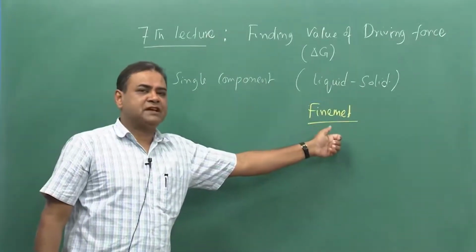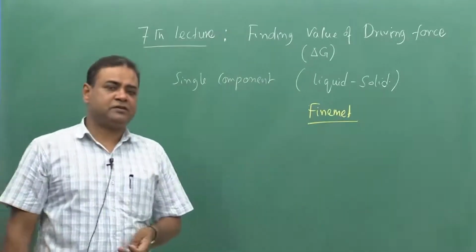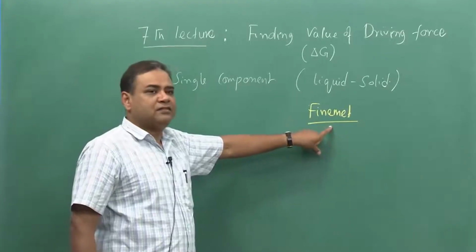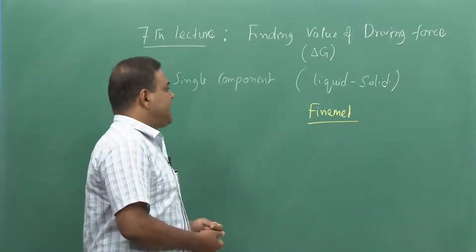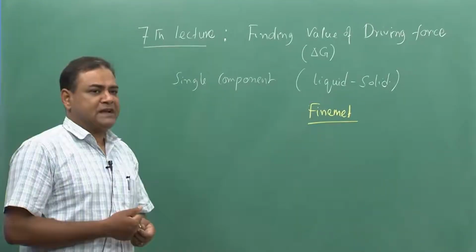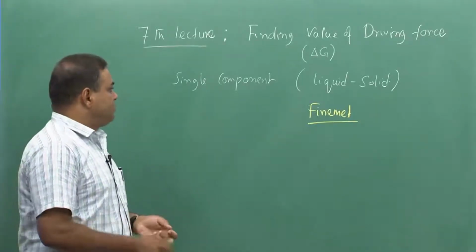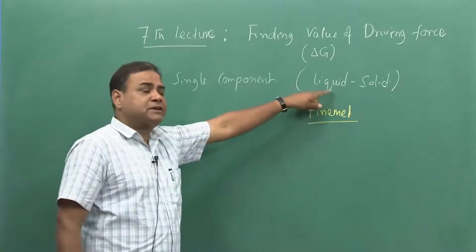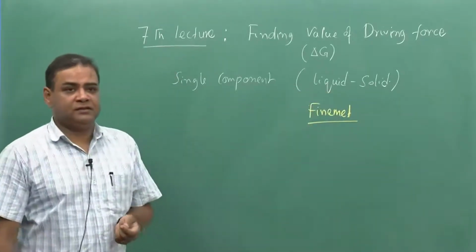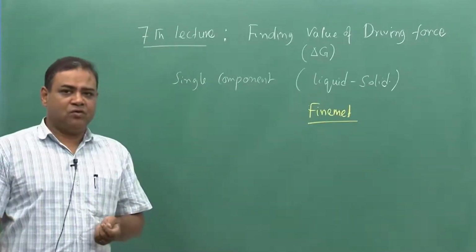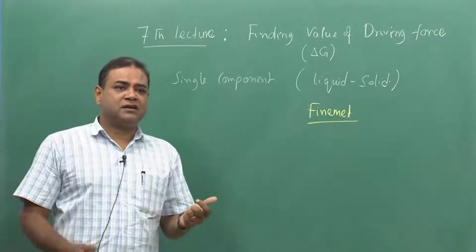One of the famous metallic glasses is Finemet, an iron based metallic glass which has fantastic soft magnetic properties. There also we try to get a glass in solid form, and later modify its structure by crystallizing, so as to improve its soft magnetic response.